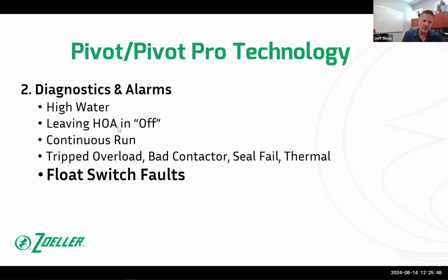Normally, you'd be in auto when you leave because you're letting the panel listen to the switches as to whether or not to turn the pump on and off, right? So if you put it in hand, or let's say you put it in off because you're servicing something, and you do your thing and you clean up the site and you close the door and you leave, you forget to put it back in auto, that's a bad day. And that happens all the time because the next phone call that contractor gets is somebody pretty upset with the sewage that's backing up in the basement because they left it off.